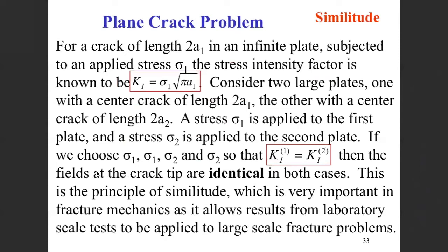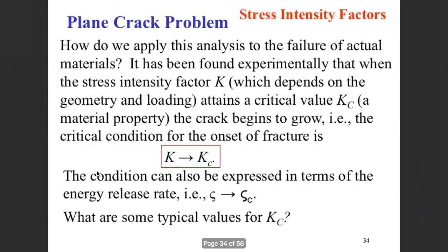And this is something I think that's sort of lost in a lot of elementary discussions of fracture, right? If you go back to, like, again, Introduction to Material Science or your undergrad mechanical behavior course, right? This is, I think, in my mind, the key idea of why a stress intensity factor is useful. And this is the principle of similitude, which is the key word. Right?